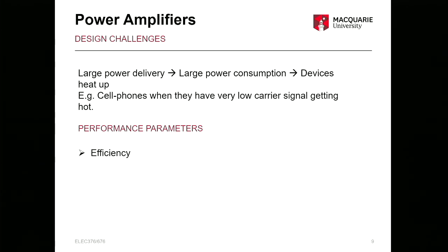So the performance parameters to focus on: efficiency, of course that's key, linearity, because otherwise we get distortion in our signal, and you can imagine we don't want that in our audio in our speaker. We don't want distortion in our transmission of our voice or anything like that. Distortion is going to corrupt it. And delivered power, that's the other main parameter. So you want to be able to deliver high power linearly and efficiently. Okay, those are the three key parameters.